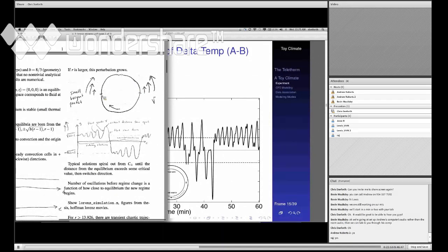So since it sped the fluid up, it spends less time cooling. All right, so we have a warm pocket that spends less time cooling. So when it gets over here, it's warmer again than it should have been and than it was last time. And warm things like to rise. Now the fluid is carrying it around in the loop due to its momentum, but it wants to rise because it's warmer than it should be and warmer than its neighbors. And so it decelerates the fluid, and that's what this little arrow is meant to represent.